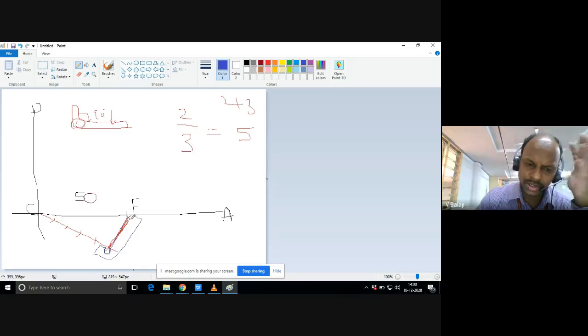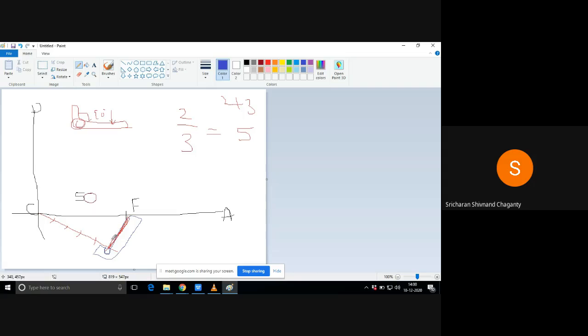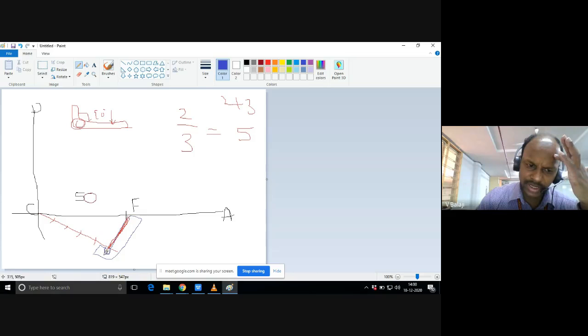The shorter one you need not worry about. Neglect that. Just match the longer scale, tighten the mini drafter knob, and hold the knob gently. Just move the mini drafter from here to here. You need to draw one more parallel line to this original line. That is the advantage of the mini drafter. Just move the drafter from arc to arc and draw parallel lines like this.